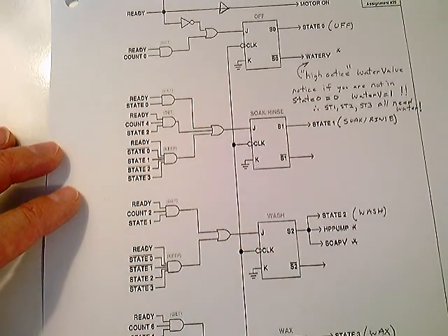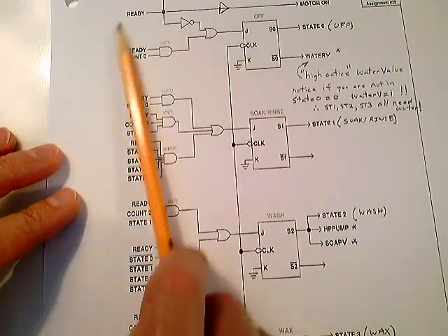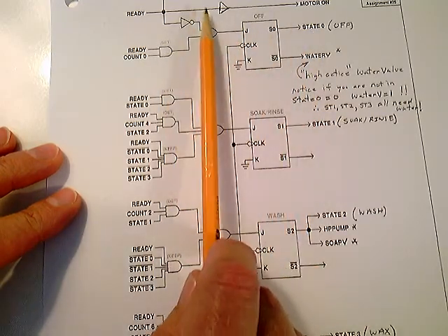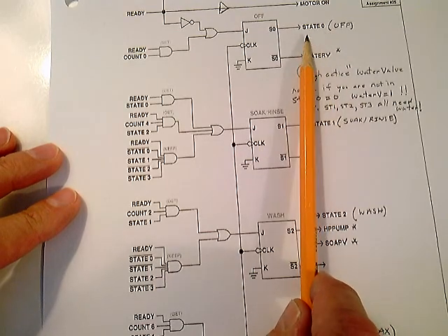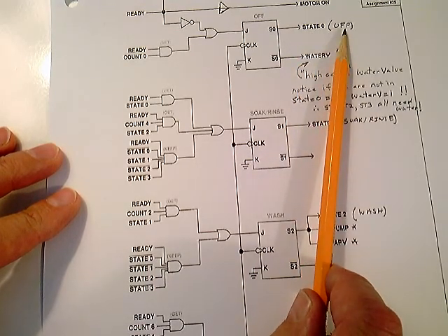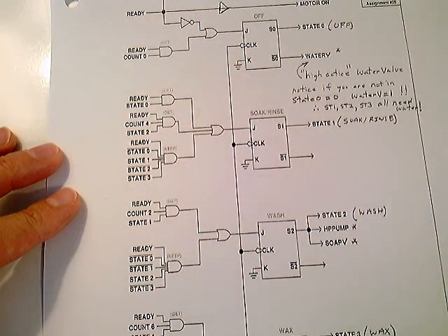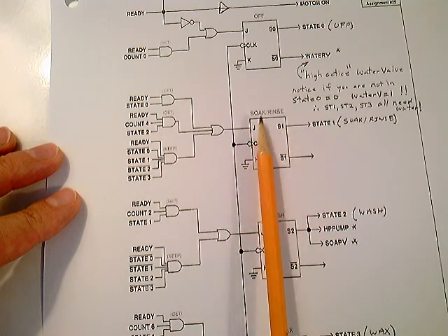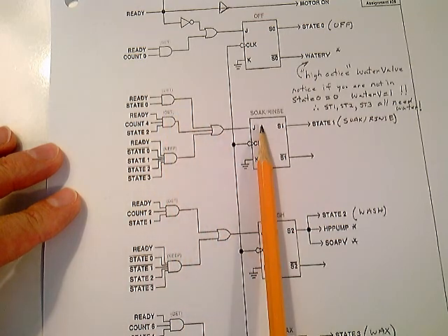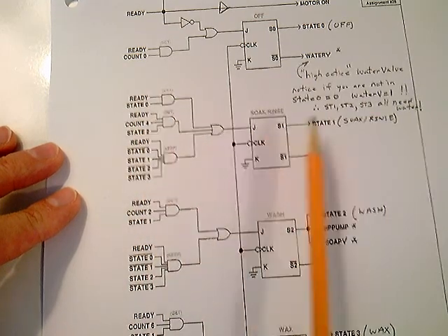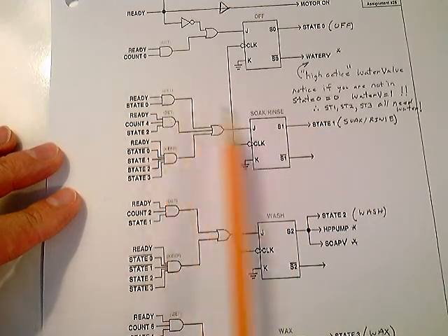Look at all this. But here's your J term. This is your get terms. This is what gets you into state, or this is what gets you, or keeps you into state 0. But that's the off state. We already know. We have that set up already from the previous comment I just made. But what gets you into the soak or the rinse state? Well, these terms get you in, or these terms get you in. That's what gets you into the soak or the rinse state. Look at the state transition diagram. You'll see this. This gets you in, or this gets you in.